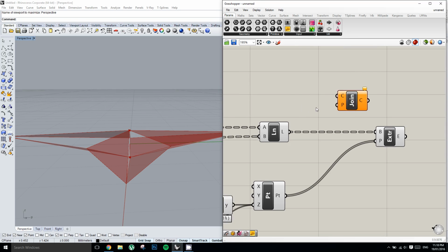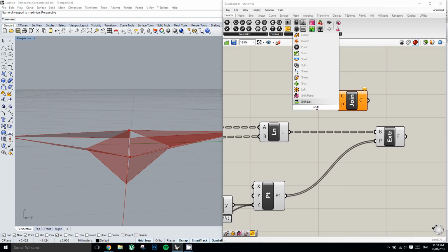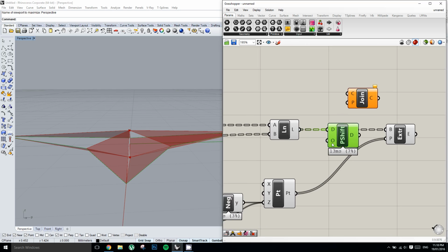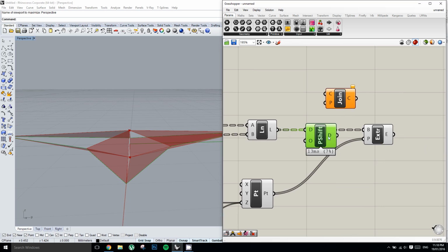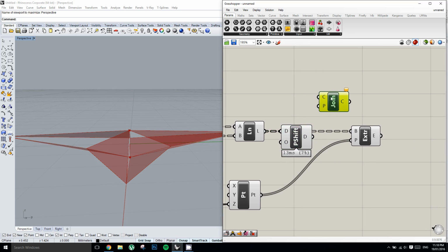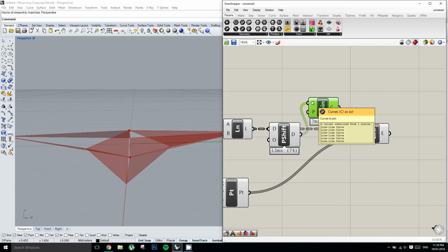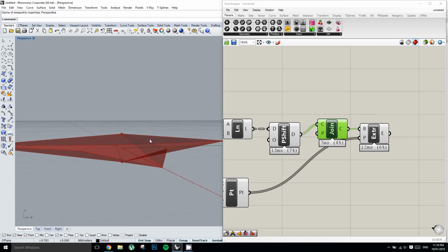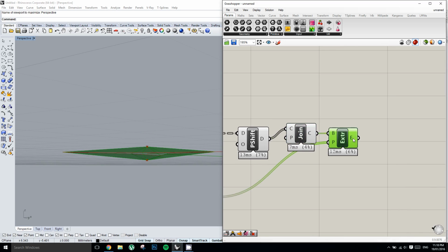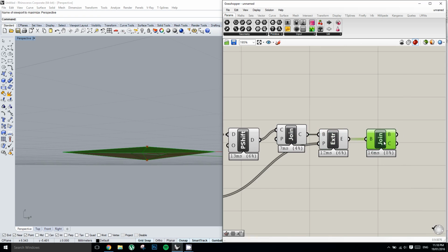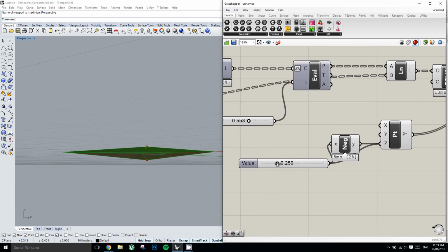We're also going to shift the paths back, which deconstructs our hierarchy a little bit. Now we have 6 curves joined into one closed curve, and that will be extruded both positively and negatively. And now we can use a break join component in order to make this into a solid piece of geometry which we have full control over of its height.